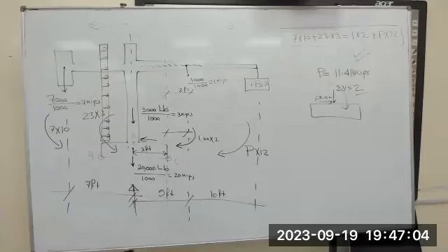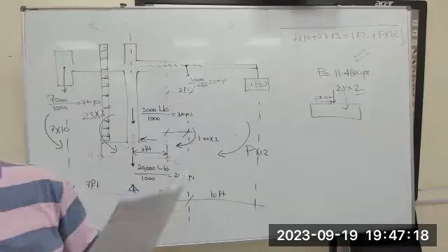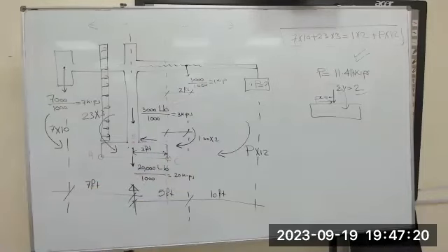It means a section to make it economic. So it means what? I need to reduce. Hot rolled section is standard. Correct? For a huge warehouse it is better to go for PEB or hot rolled pre-engineered.